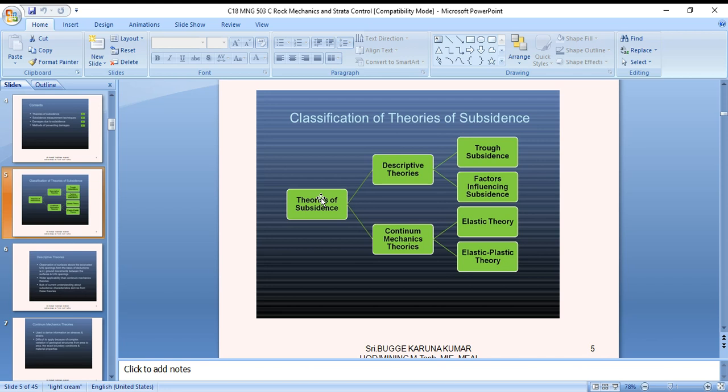So gravitational and possibly tectonic forces act on the rock surrounding an underground excavation in such a direction as to close the opening. A part of this closure results from the elastic, time-independent deformation, apart from the inelastic, time-dependent deformation. In many instances, a substantial part of the closure is due to the fracturing of the overlying rock, which falls into the opening. Collectively, these effects tend to produce a lowering of the rock overlying the opening, and this process is referred to as subsidence.